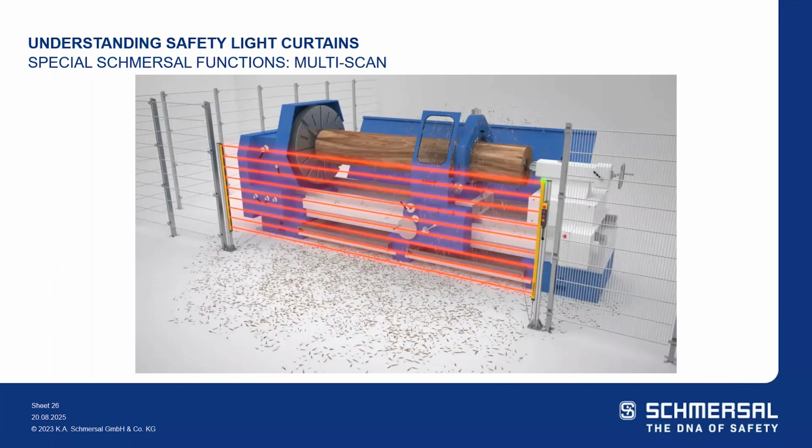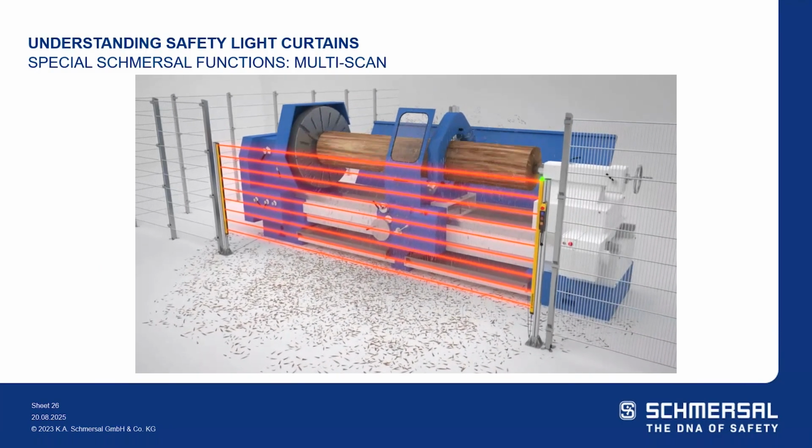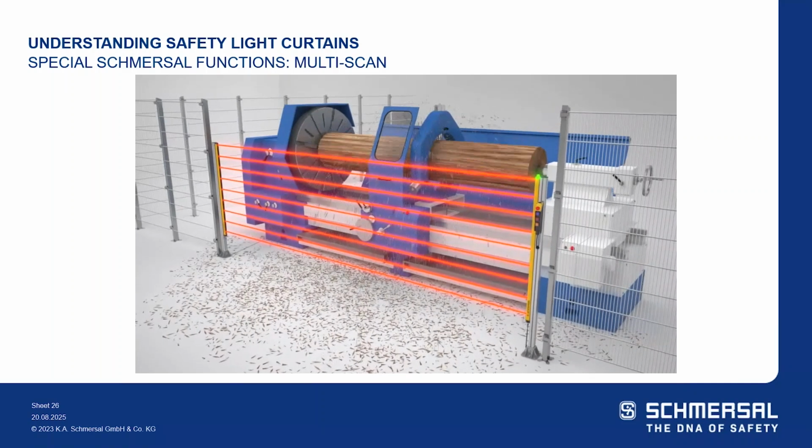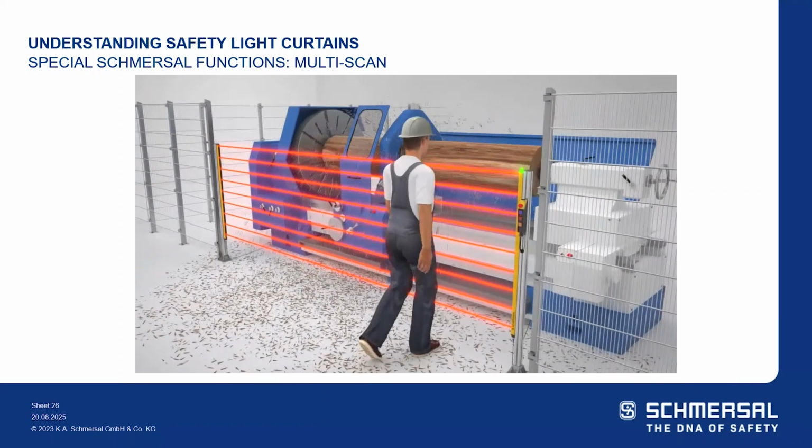Multiscan. Multiscan prevents forced trips or unintended stop commands. In essence, the light curtain is scanned multiple times to see if the interruption is still there. So multiple evaluations of that protective field would allow smaller material debris, steam clouds, or even insects to pass through the field without triggering a machine stoppage.